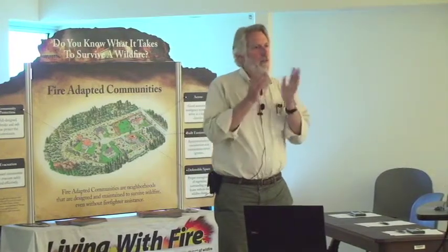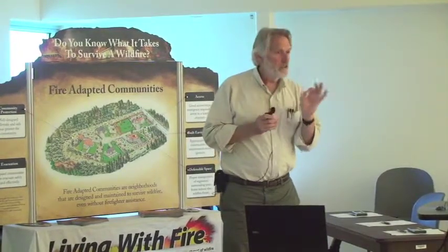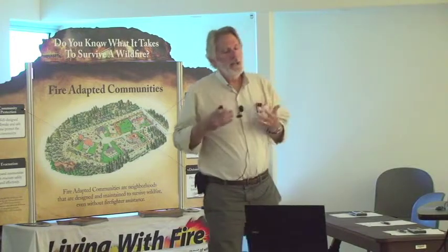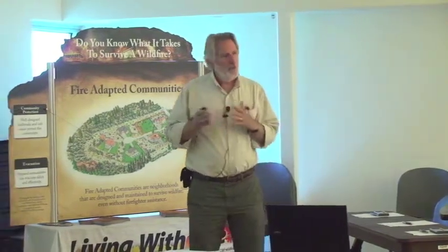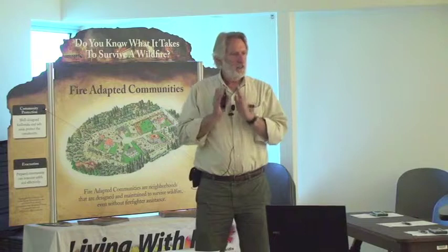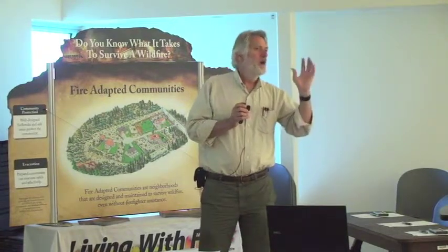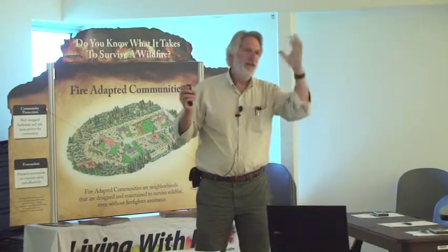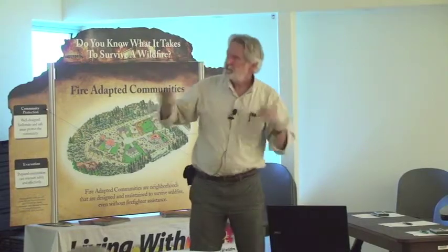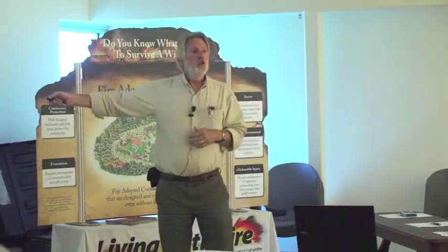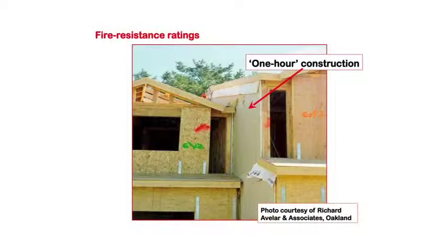It's not really 1 hour resistance, but it's just a nominal rating that provides a relative comparison of how well a given construction resists the fire moving from room A to room B, or attic space A to attic space B. And typically you do this using specialized gypsum wallboard. So in this particular example, we have gypsum wallboard on the exterior of this unit and also on the exterior of this unit. So together, there's two pieces of gyp right together.